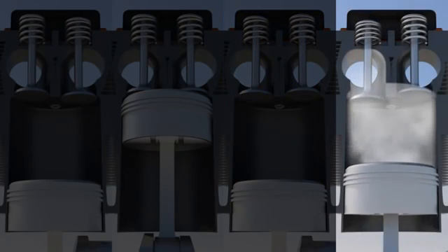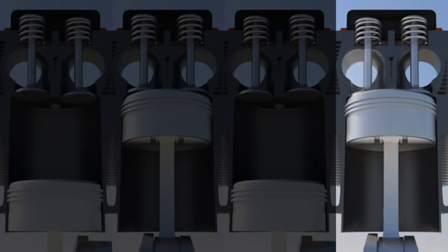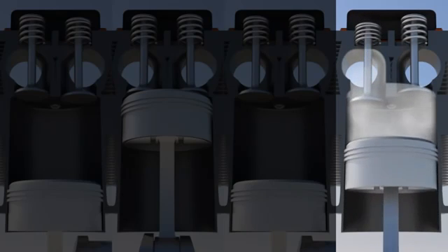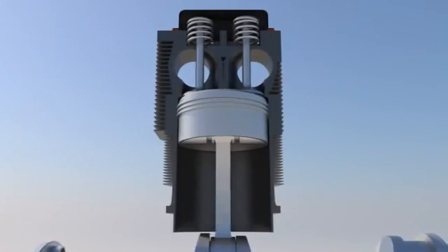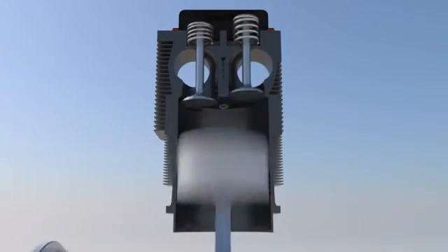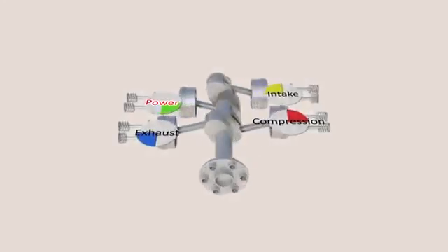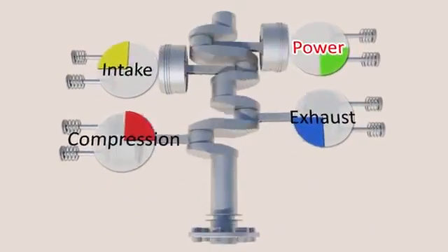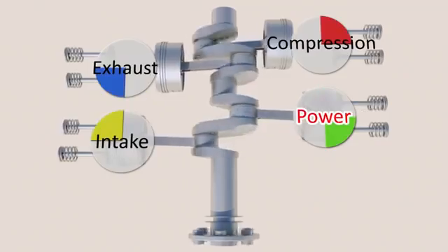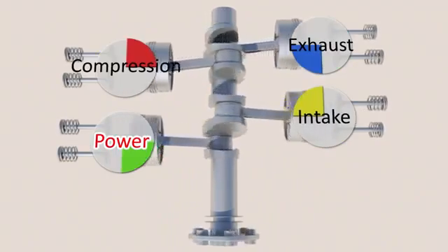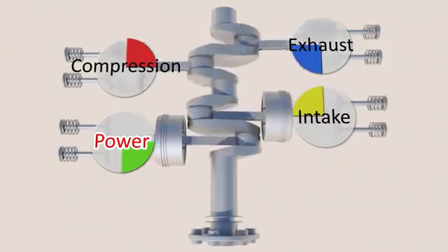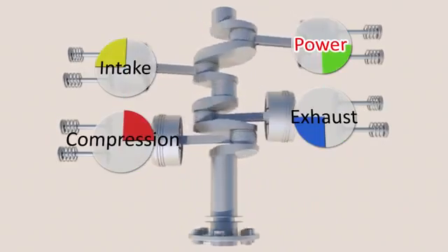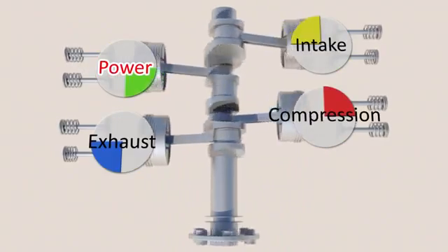During this phase, the exhaust valve opens, and the piston moves back towards the cylinder head, pushing out the combusted gases, commonly called exhaust. Then the process starts all over again, repeating thousands of times every minute. On a typical four-cylinder engine, each one of the cylinders is in the middle of a different stroke. That way, one cylinder is always in the power stroke, and the engine is able to keep the crankshaft rotating, thereby allowing the remaining cylinders to go through their respective stroke.